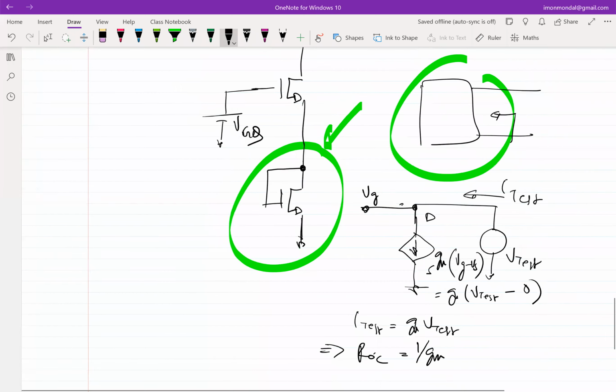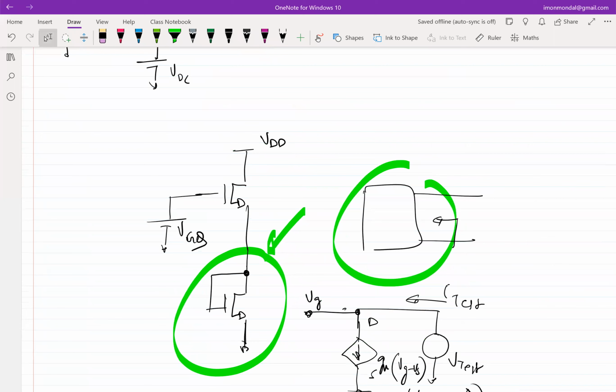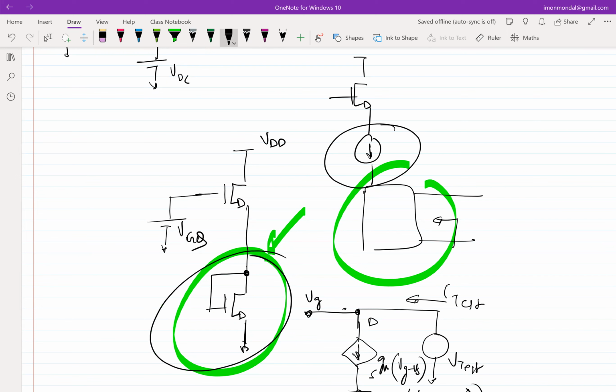No, so I wanted to figure out whether I can replace the current source with this diode connected one, right? So I'm trying to figure out what this is. If I replace this with this, then I am trying to figure out whether the stuff that I have replaced it with is a good current source or not. So that's why I'm not bothered about the upper part, right?